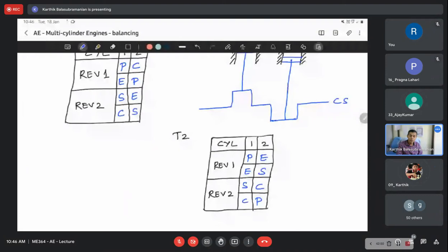Are you getting it? Yes, sir. So now what happens if we go for a four-cylinder engine? We can get 4 power strokes, sir. You will have 4 power strokes and then you can time it appropriately. See, the crankshaft is common, try to understand. The crankshaft is common, but you are going on increasing the number of cylinders. So now the crankshaft is going to experience more number of power strokes. If I have only one cylinder, the crankshaft will get 1 power stroke for every 2 rotations,